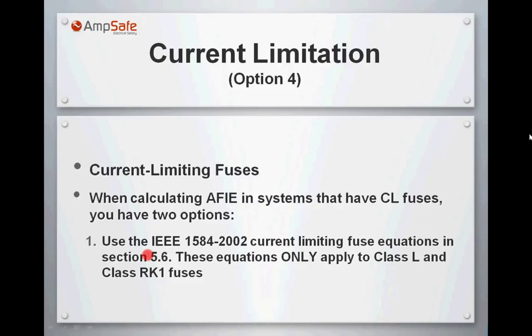So you have that option of using the specialized fuse equations instead of using the time current curve to determine the arcing time of the fuse, and of course applying the normal equations from IEEE standards.